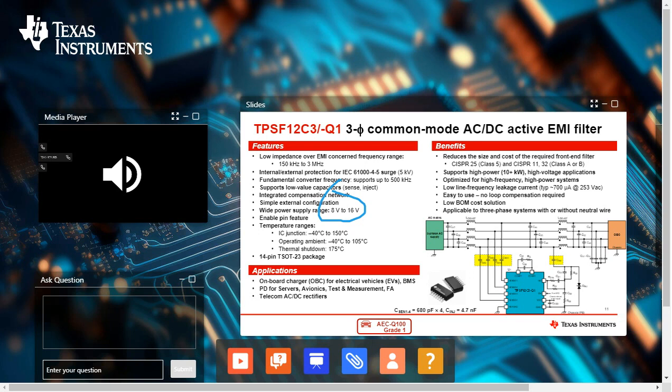In the three-phase four-wire system, each of the three lines and the neutral are sensed by sense caps that are Y-rated for the common mode voltage perturbations. However, only one Y cap, highlighted here, is needed on the inject side.